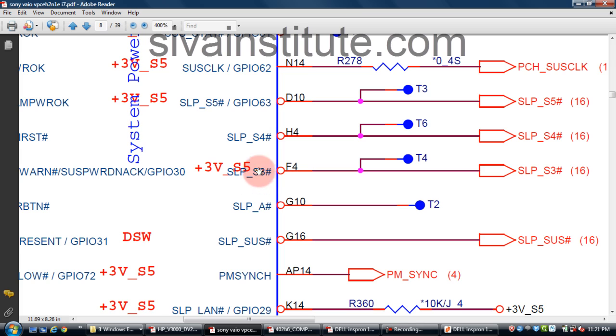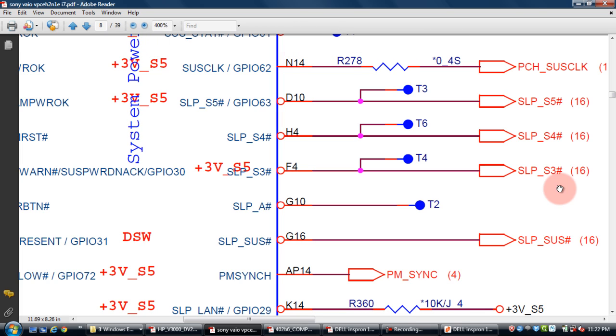When this voltage comes out from this place, the ICH voltage goes to 3.3 volts. When this command comes out from this place, the memory voltage comes out from that regulator. When this command comes out from this place, the voltage goes to all regulators. After all voltages come out from those regulators, this is the main procedure. Every chip has these commands.